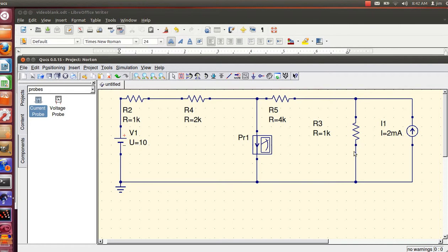So this is one unknown current. This current and this current are the same, but they're unknown. This current is an unknown, and then this current is an unknown. From circuit analysis using Kirchhoff, that means I have to have four equations. I use two current equations.